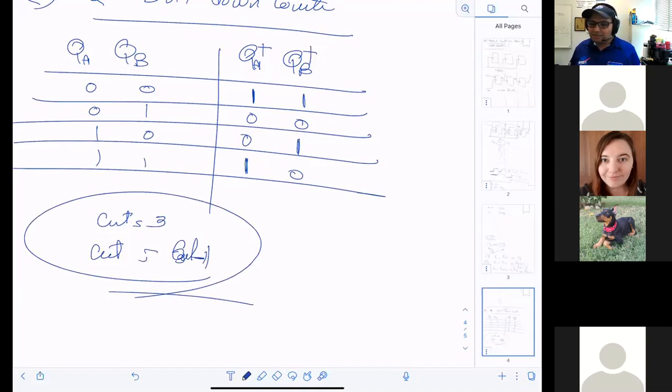If you're decrementing, isn't it 3, 2, 1? But you are starting from 3, so I'm going to go 3, 2, 1, 0 and back to 3. So I'm decrementing, but while I'm decrementing, there is a corner case. By the way, later on, when you go to the higher level courses, you're going to hear about verification and testing, and there you have to look at corner cases. But don't worry about corner cases now. We care now about the fact that the counter is a ring, right? So there are edges. When I reach one of the edges, for sure I will go back to the other edge, right?